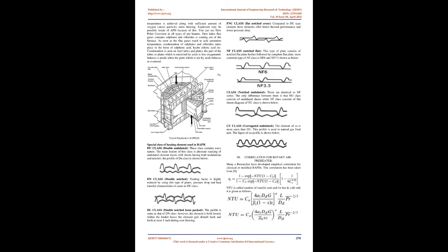You can determine approximate air heater leakage based on gas inlet and outlet analysis. Plugging and erosion: when high-speed dust particles move over materials, they remove its layers, called erosion, whereas closing down and fouling of heat transfer flow passages by gas is dominated by corrosion products and ash particles. Dangerous results of erosion are observed, such as loss of heat transfer area, structural weakening and perforation of components. Erosion could be controlled by decreasing the velocities and clearing the affected material, galvanization.